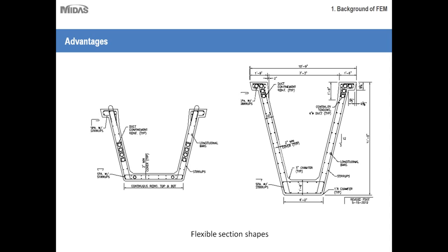And that is the biggest advantage we can get out of concrete, that we can cast it in different forms. If you are varying your span lengths and you would like to go for a tapered section from the center of the bridge to the pier support, you can very well get that kind of configuration.